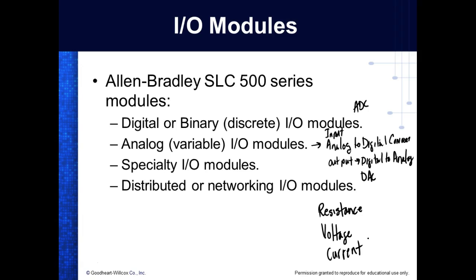So we could go back or we could look up the 500 series and look at what modules are available with this PLC. And you see it's got all types of modules, just besides what? Digital input and digital output. Now these modules we have up here, these are digital. And the PLCs, I'll hook up one of the 1100s, this guy down here, and let y'all see basically analog. It's got analog inputs on it.